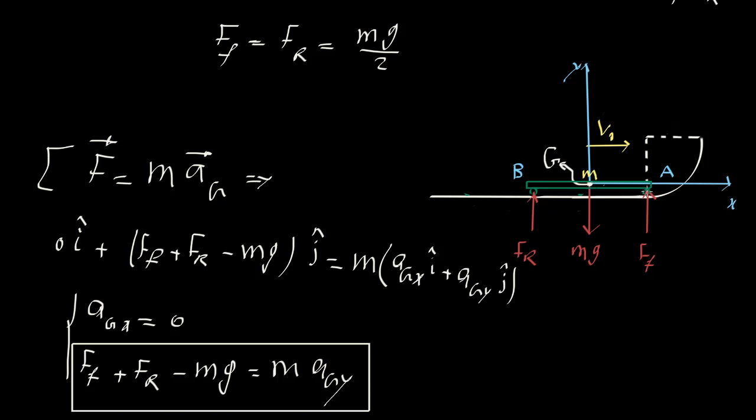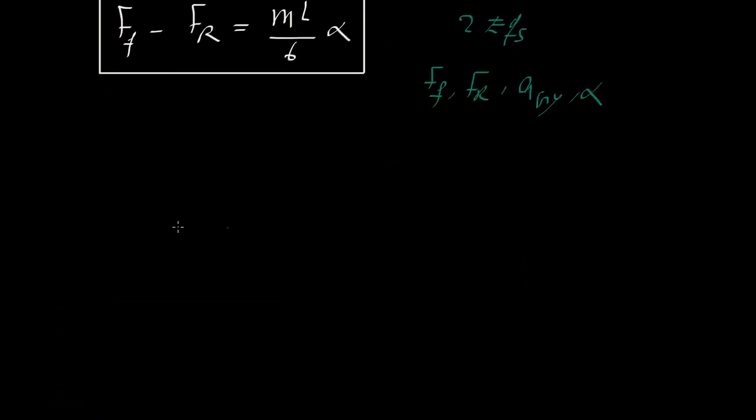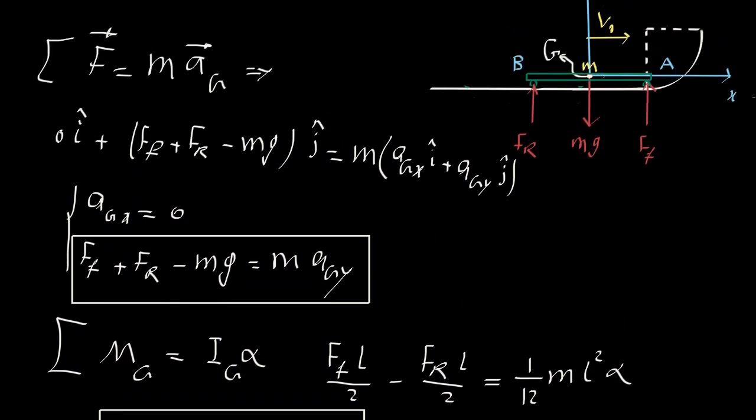So here I'm saying that we should be able to figure out the acceleration of this point A. This is a rigid body, and we can calculate the acceleration of this point on the rigid body. So nothing is wrong with that. So let's calculate a_A. So a_A would be, and we want to write the acceleration of point A based on point G, and also based on the geometry of the path.